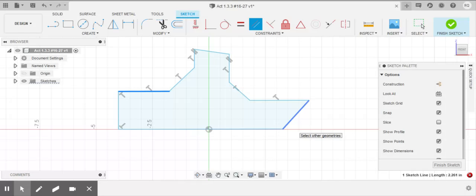Determine if the following restrictions are satisfied. We already made 1 and 9 parallel. 6 should always be parallel. Okay, I think 19 was pretty much all done based on what I just did. All right, number 20 says add geometric constraints. Okay, we just did that already. Okay, for 21, it says to create a quick sketch of the profile and show the constraints that you added. So go ahead, take a moment, pause the video.